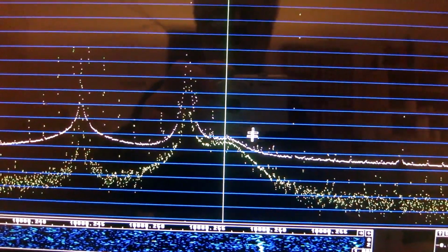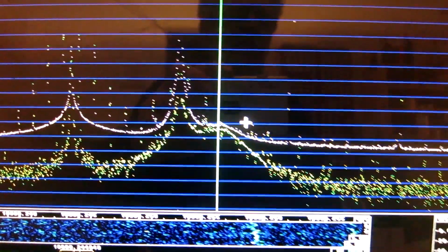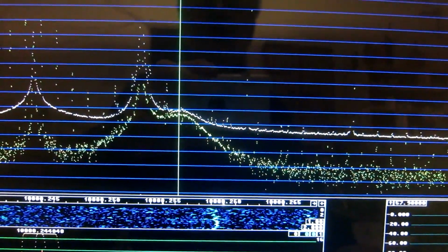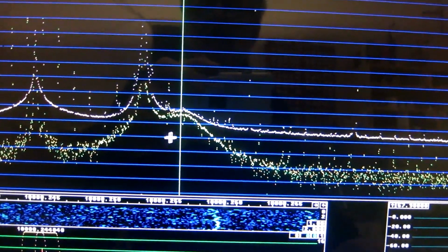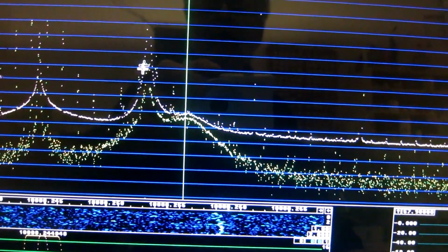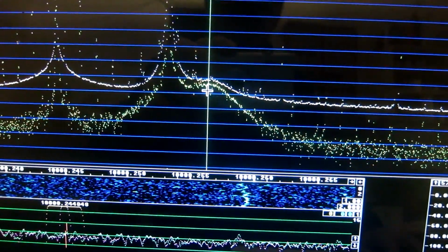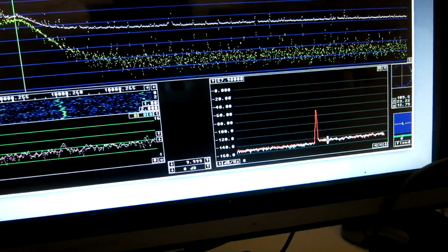What I see is totally unexpected to me. This filter does not remove noise, it adds noise. The crystal is pumped by the carrier here, and it gives noise on its own resonance frequency. And I can read what is the sideband noise level.